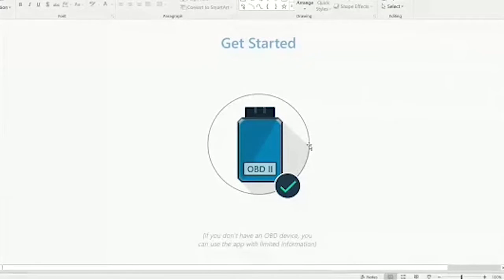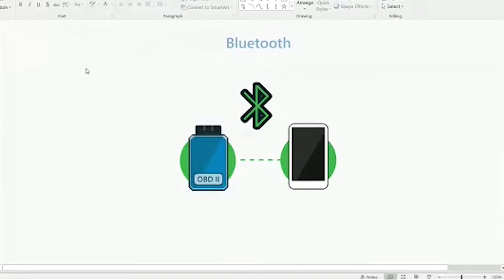You plug it into your car, and usually this dongle has a type of connection with an external system that could be via Bluetooth. In this case, I can connect from my smartphone, or in my case, from my AutoSense system, directly to the plug, and communicate with it in a normal serial messaging system.